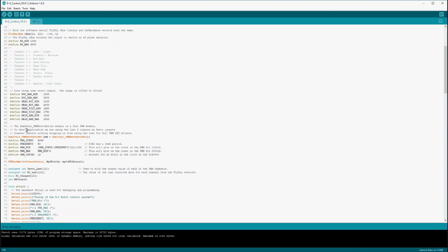Now let's look at the Adafruit PWM servo module. Now the chip they use in this was first and foremost designed as an LED driver, and it is a full proper PWM driver with the full range of 0 to 4095, so 4096 steps. By default it runs at 200 Hertz. We're dropping it back to 50 Hertz.